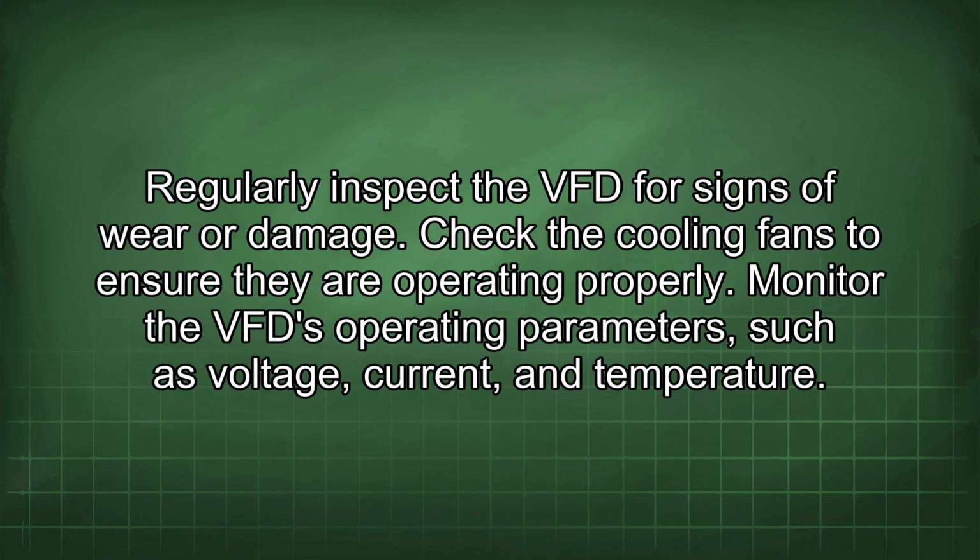Regularly inspect the VFD for signs of wear or damage. Check the cooling fans to ensure they are operating properly. Monitor the VFD operating parameters, such as voltage, current, and temperature.